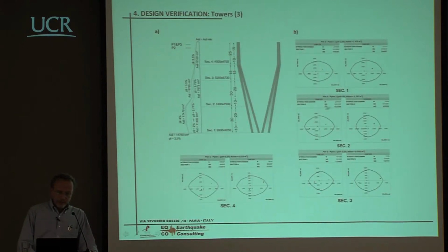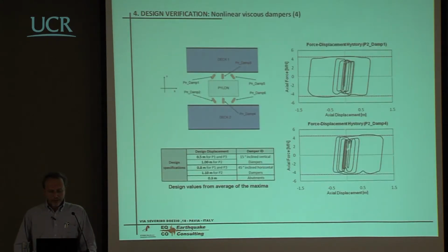And then you check all the capacity of each one of the sections with respect to the action. And when you do something like this, you still try to have values of the forces that will anyway allow some nonlinear displacement, even if this is not the case, because you may have some unforeseen level of action. But this is another story.